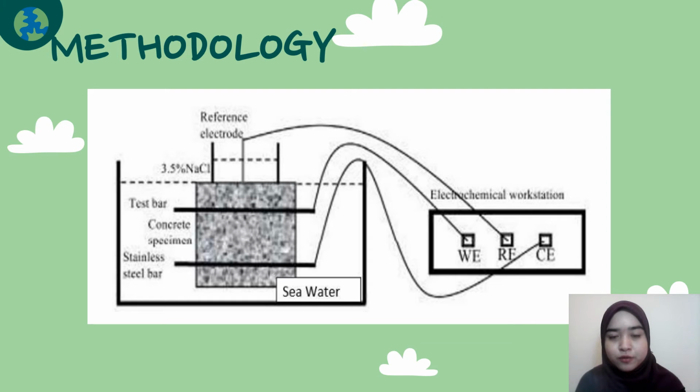Next is the methodology. This is the proposed experimental setup. I will use the electrochemical workstation, or it can be replaced with an alkaline battery, because I want the power supply to undergo the electrodeposition method. The concrete specimen and stainless steel bar will be submerged in the seawater and will be added with calcium carbonate powder. Calcium carbonate powder is added because it is the base for our artificial coral reef.